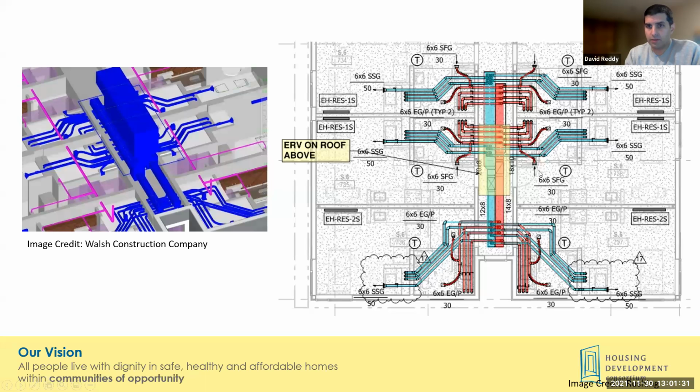This is the range hood here, and the bathroom. So that meets the criteria for a distributed system. And this was driven in part by the passive house goal, very, very tight building envelope. You can see it eliminates any exhaust ductwork from the range. There's a recirculating range hood for this building design.